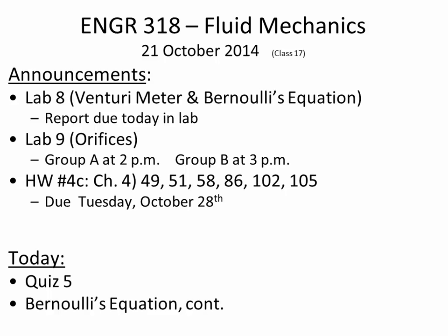I'll give everyone a piece of graph paper that you can put behind the pins that are going to trace the jet. I don't expect everyone to necessarily put their paper behind there and trace it, but you can if you want. We'll have enough time, and basically from that trace you'll be able to find the discharge coefficient for the hole, and that's related to how much energy loss there is as water flows through an orifice. So please watch that video before lab today.